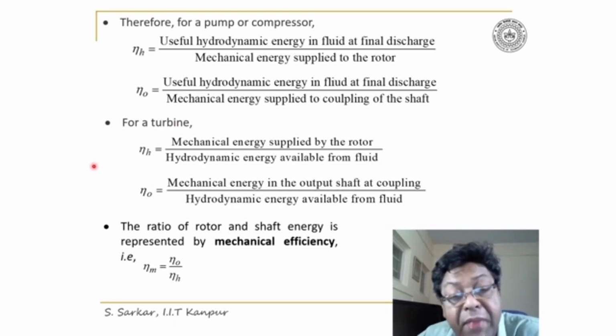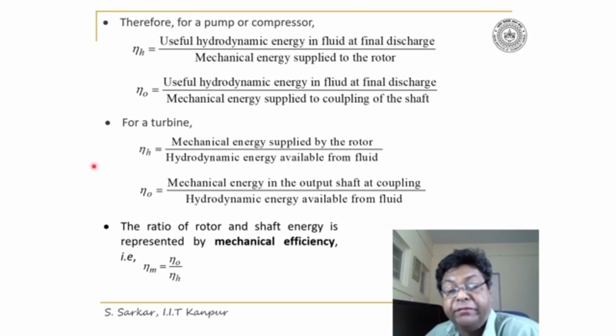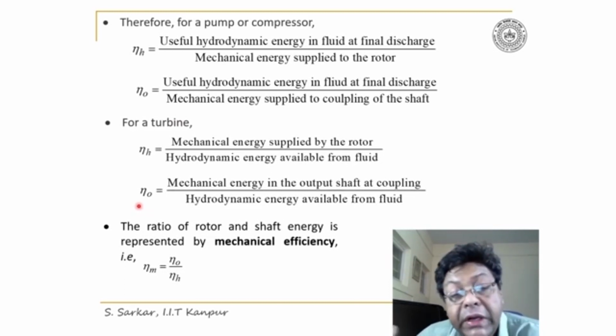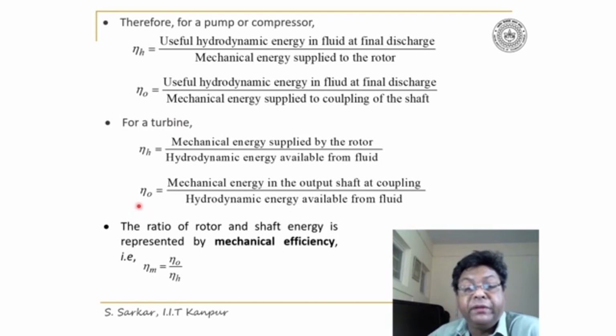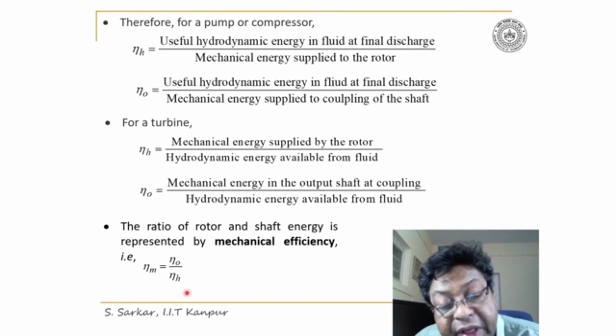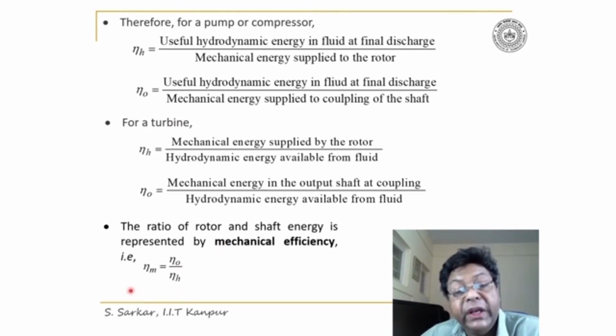I have stated this as the instantaneous rate of change of phi in the system is equal to the sum of the time rate of change of property within the control volume plus the net rate of efflux of property small phi across the control surface. I have discussed here the application of Reynolds transport theorem.